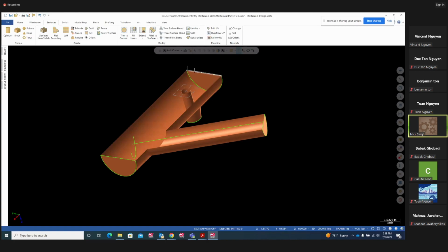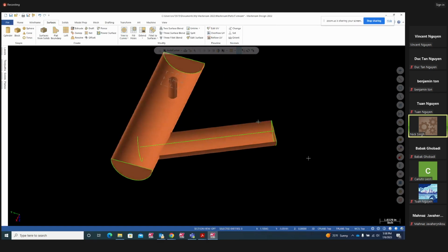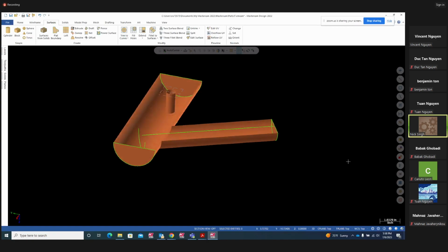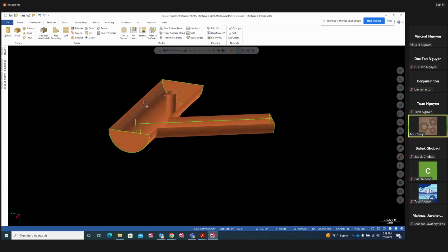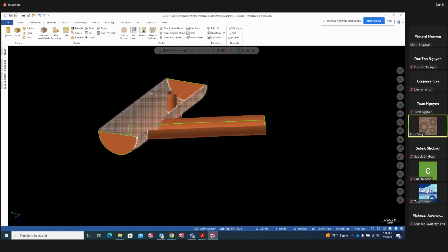We have only geometry right here on this edge, and on this edge, but there's no geometry on this edge, and this edge, and this edge here either. To create a flat boundary surface, you have to have closed geometry, a chain. So once we have a surface and we don't have a curve or any geometry, we can create one from the surface's edge.